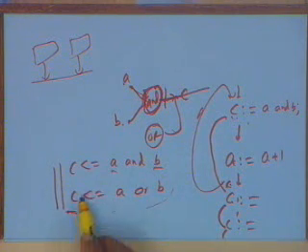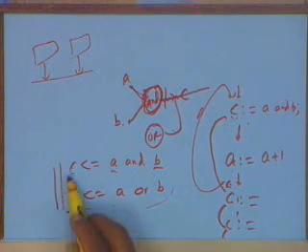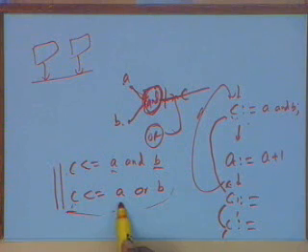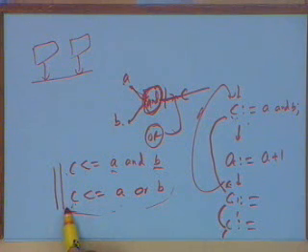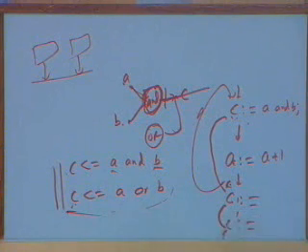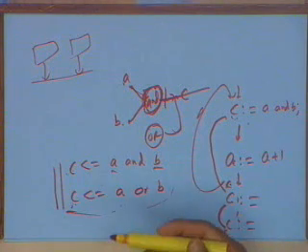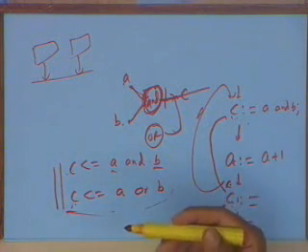So you cannot write multiple statements where the same port or the same signal appears on the left hand side again and again. There is no problem in appearing on the right hand side, but there is a problem in appearing on the left hand side, which is very different from the way the programming language works. So this is a very fundamental difference between signals and variables, and typically you write your VHDL using signals, and